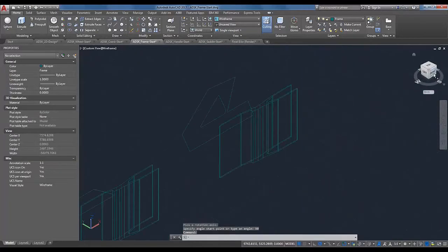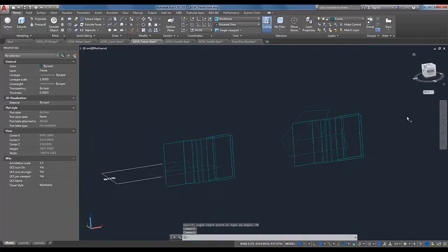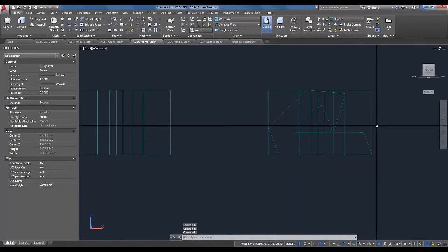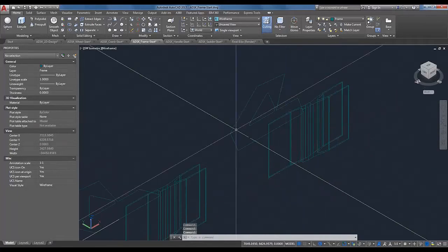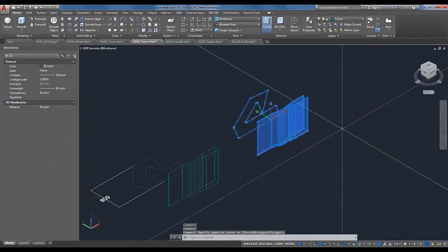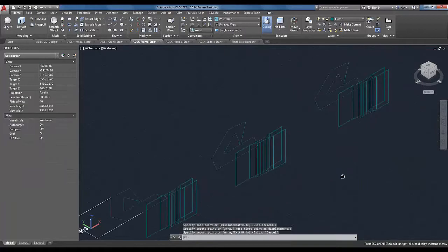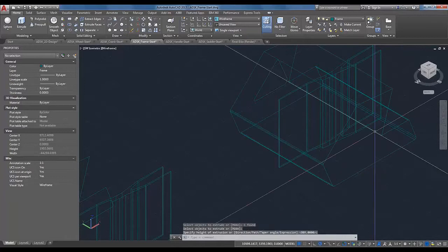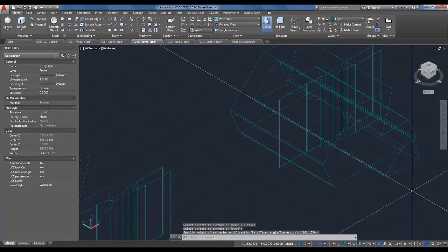So now if I look at it in front view, you can see that they're overlapping each other pretty cleanly. Had I not done the 3D rotate on that bottom axis, it would have been shifted down. It would have been occurring somewhere down here. So again, that was something that I really wanted to do, just to stay organized with our design. I'm going to copy this over. And again, I'm going to extrude these two design elements through my frame.